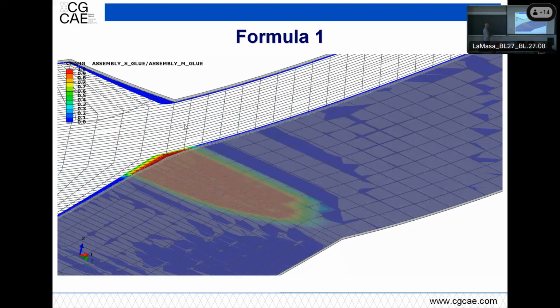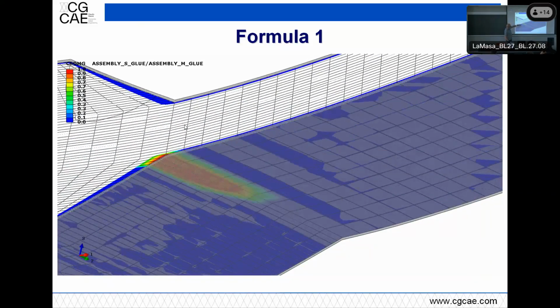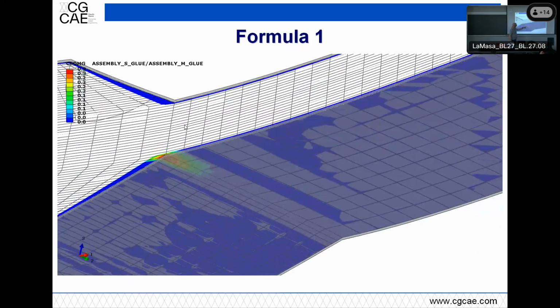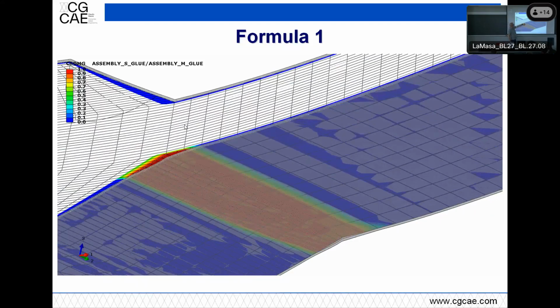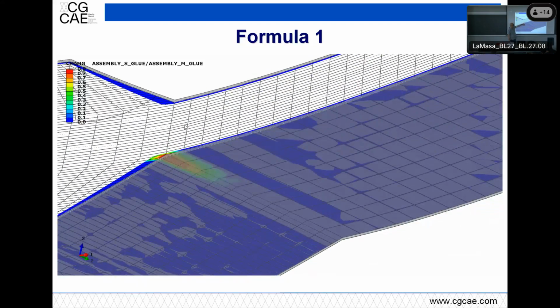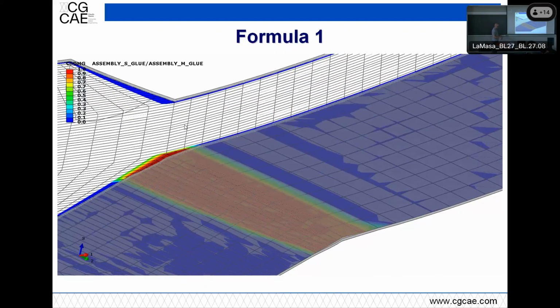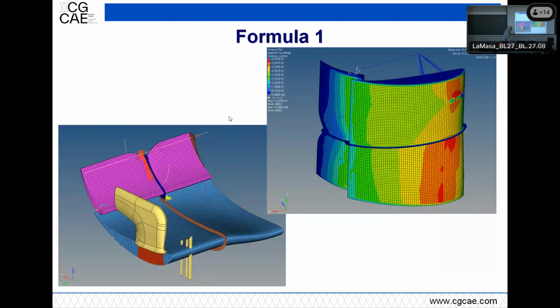Also, this one I did later in the past, simulating again the bonding of these two plies with respect to the rest. You can see, this is a plane cut in the middle, that indeed it's happening, the plies are opening, and it doesn't progress, because very likely, when you come to a certain point, the sigma z gets below the allowable of the resin, and so it stops. Not nice to see. So I did the same thing for the old model and modified the new until I got to the same stress level as before. So reasoning by comparing could give a design change, which then made the parts survive.